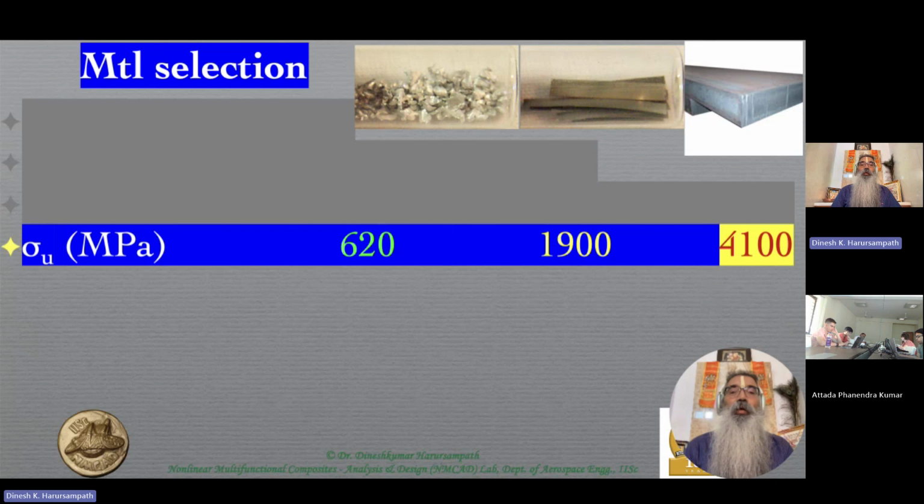So if you're looking at it purely from a tensile performance all the way to failure, remember, ultimate tensile strength is beyond the proportionality limit and also the yield strength, and therefore it has already gone into the plastic regime. This is the final failure of the material. You rarely will go all the way up to it, but it's important to be aware of these numbers, not exactly, but at least in terms of an overall relative sense.